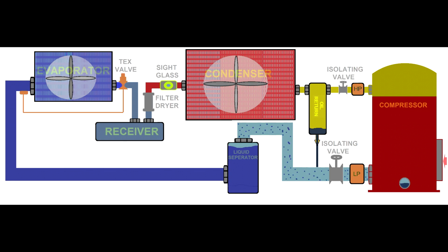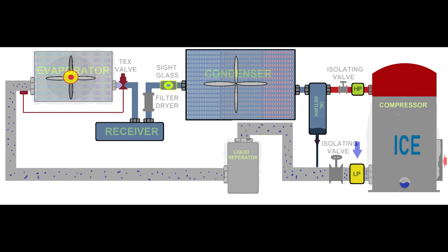If you overcharge the system, that's worse. If you overcharge the system too much, the liquid will come back into the compressor crankcase. See? If you look at the lower side, the liquid separator is full, and then you will wash the oil out of the compressor crankcase and you will destroy the compressor.